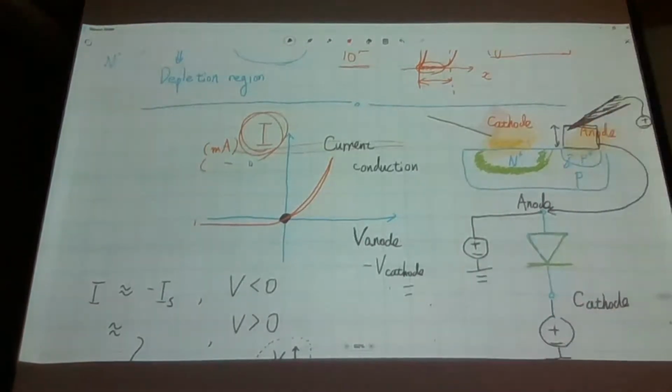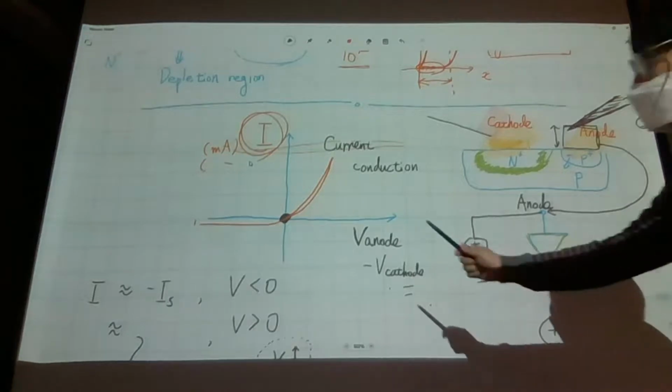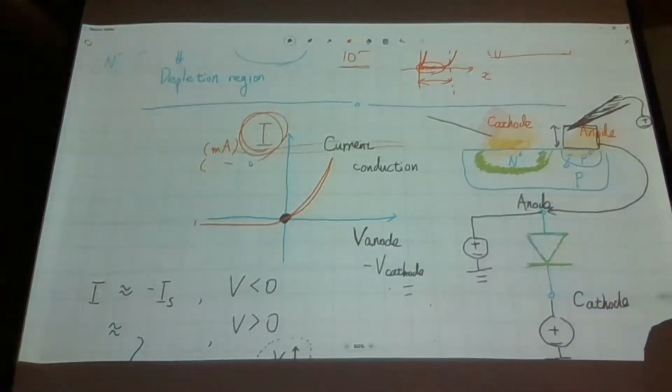So whether that is important or not is determined by the scale. If you care about femtoampere current, then that will be really important. However, if you are talking about just the ampere scale or milliampere scale curve, then this guy can be safely regarded as just nothing. So please keep in mind that when we consider this forward bias current, what is your range for current conduction? That will be certainly about milliampere or microampere scale for microelectronics, and that requires a certain voltage to make your system sufficiently turned on. Only after a certain voltage will your exponential function just fly like this.